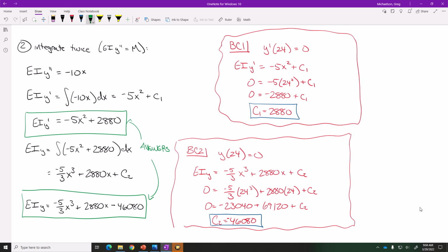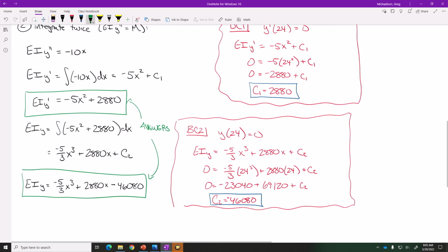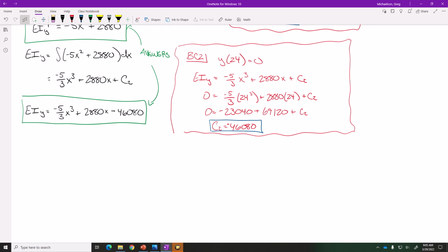Got it. Okay. Some people did. Real quick, how do we determine maximum deflection? Well, where is maximum deflection on this beam? At x equals 0, right at the free end. So if x equals 0, that's 0, that's 0, maximum deflection is just this over EI, right? So if I wanted to determine maximum deflection, where's maximum slope, by the way? X equals 0, right? Same place.